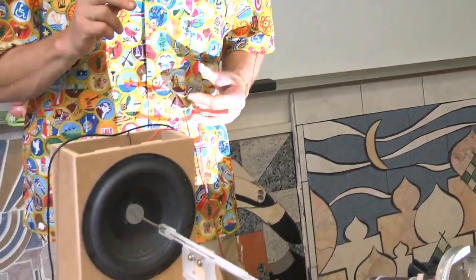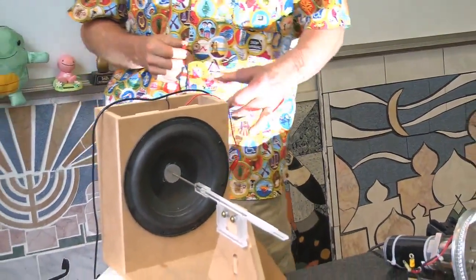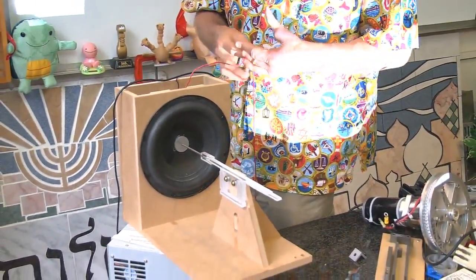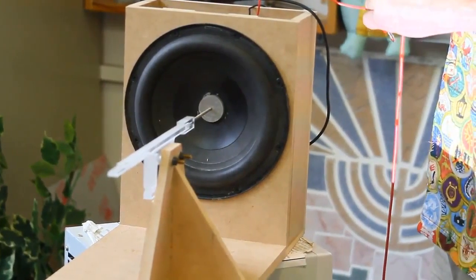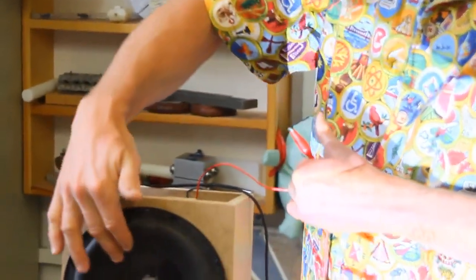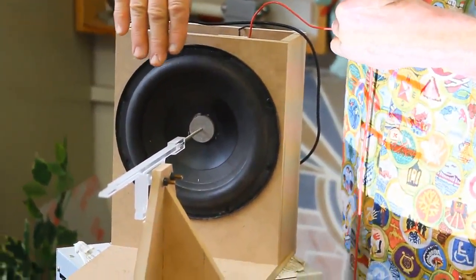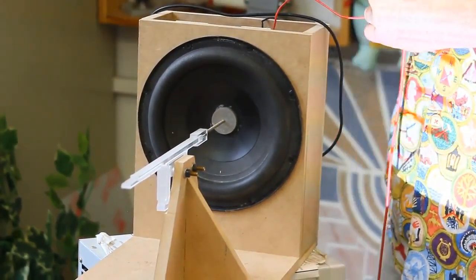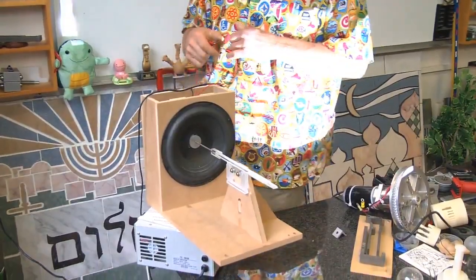So I could sing, which I won't, because we don't want to shatter the lenses, into a microphone, which would cause vibration of a diaphragm. That vibrating diaphragm in a permanent magnetic field would induce a current in the coils, which would be taken back and through the electronics amplified. That voltage sent out to the coils on a speaker, which would then cause the speaker head to move in and out and cause the air to move in front of it, hence hearing my voice again. So let me connect up this speaker and let's see what happens.